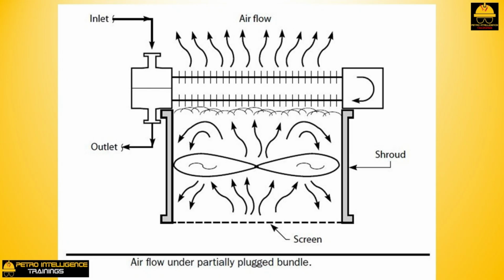Note that on the right side of the sketch there is a small gap between the blade tip and the shroud. It is this gap that accounts for the air recirculation previously described. The bigger the gap, the greater the detrimental air recirculation. With age, shrouds get out of round and the gap increases, but not uniformly.